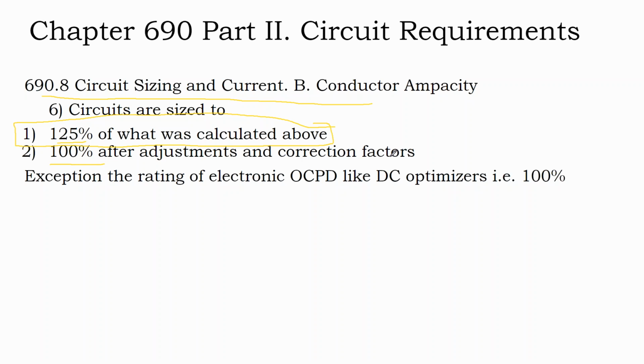And so, I guess what we're talking about is that ampacity, that short circuit current plus 25%, as you would size kind of standard things in electric code, that doesn't take into account the fact that, in addition to number of conductors in a cable, in a conduit, in addition to being 1 inch from the rooftop, in addition to all those things, the amperage itself will jump around as a function of temperature, and we're given what's listed at 25C.